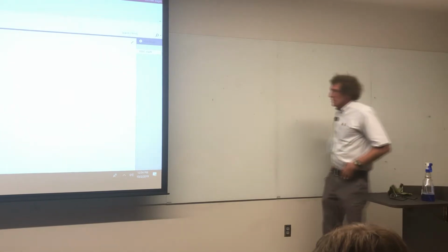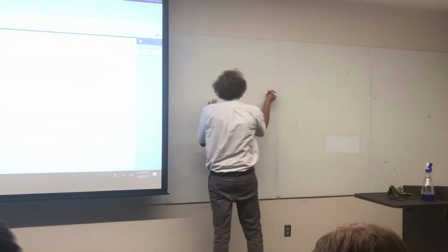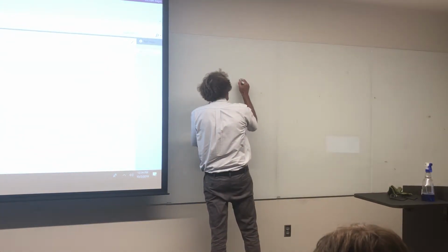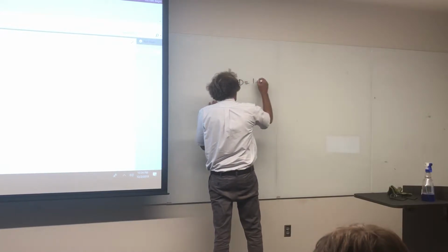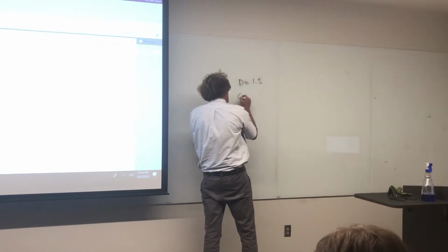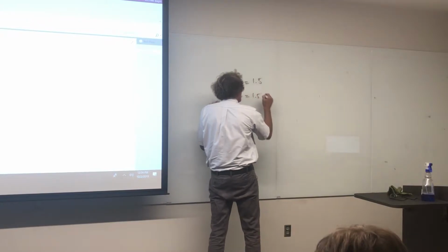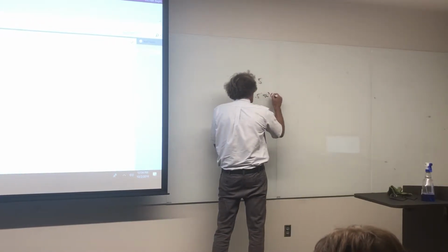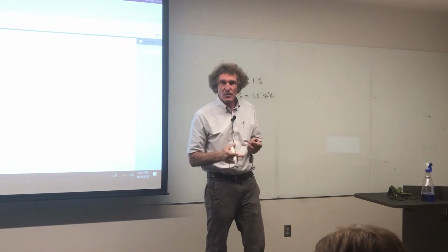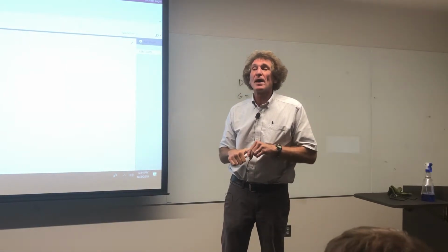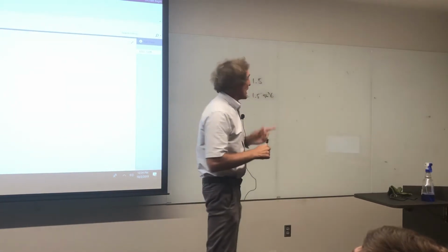For a short dipole, you know the directivity was 1.5. And the gain is basically 1.5 times the sine squared of theta, because the sine squared of theta would be the normalized power. You knew that.